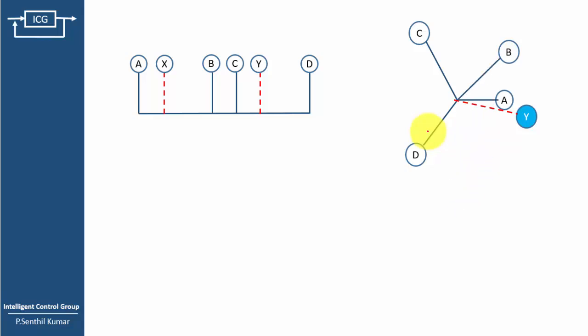So now I'm going to draw the force polygon. First mark line A, value 16, then the corresponding reduced scale factor 4. So mark A as 4 centimeter. Direction as it is. Since it is a positive value, we will take the direction as it is.